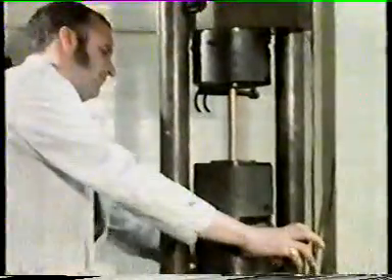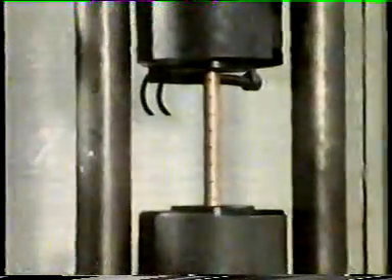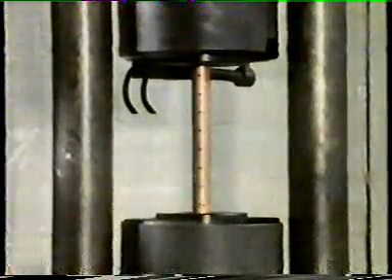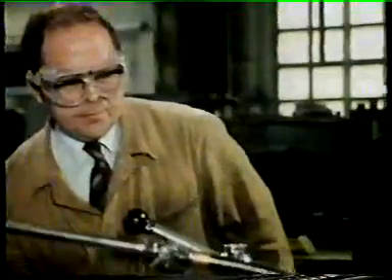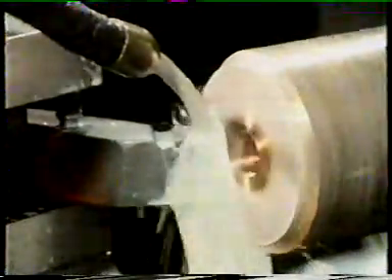What effect has it had on the tensile strength? Here we're measuring the drawn or cold worked tube. We're measuring the force in kilonewtons. That fractured at 27 kilonewtons. Now, to compare tensile strengths, we must measure the force needed to pull a similar piece of cast copper apart. We need a cast tube. But of course, we can't cast a tube. What we can do, though, is machine one from a cast billet. Although this involves some cold working, it's nothing like the amount that's involved in drawing the tube.